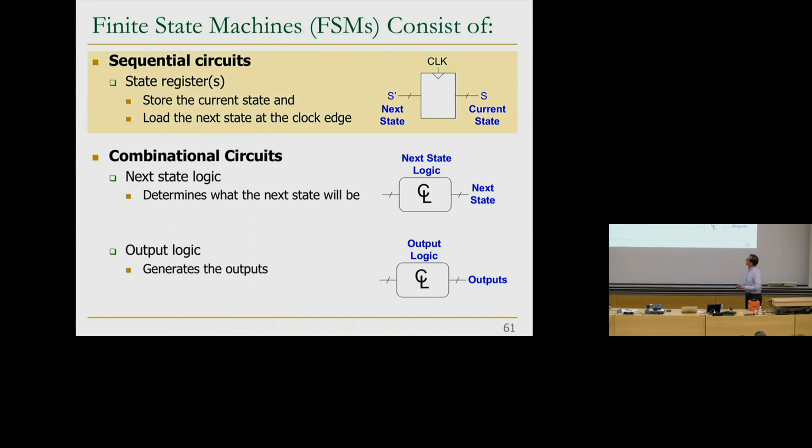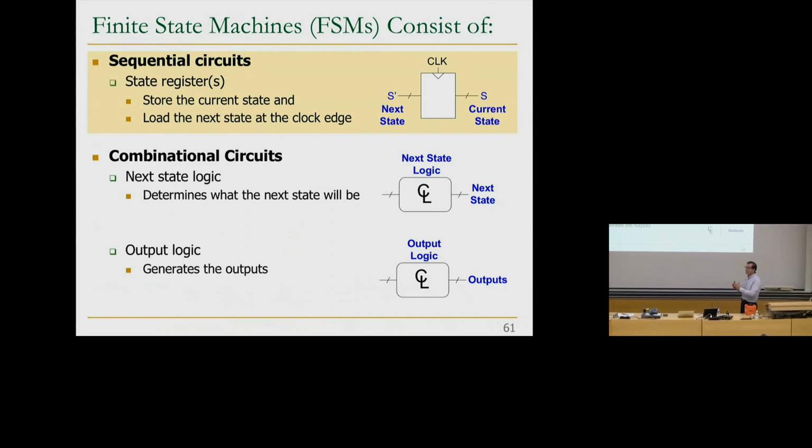So let's take a look at the state register a bit. Because what we've built so far, the latches, don't satisfy our requirements. And remember, our requirement is actually twofold. One is that your current state should be available for the entire clock cycle so that the combinational logic evaluates nicely. And your state needs to be latched at the beginning of the clock cycle.